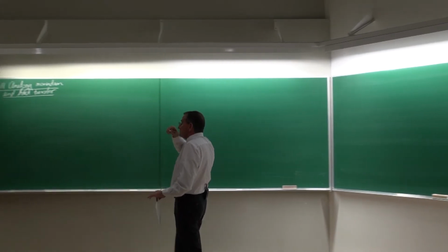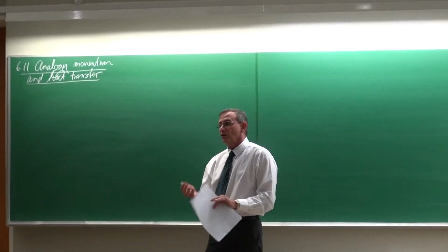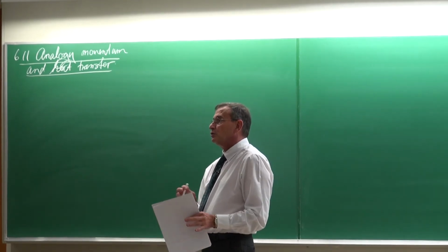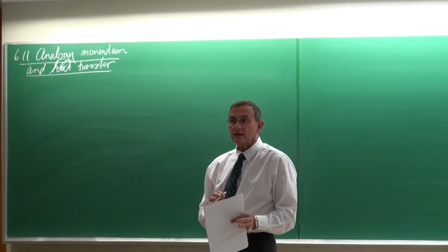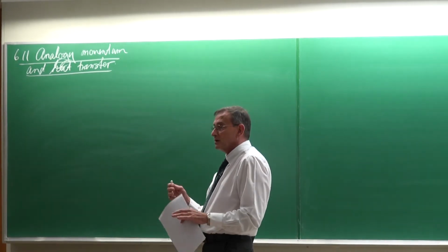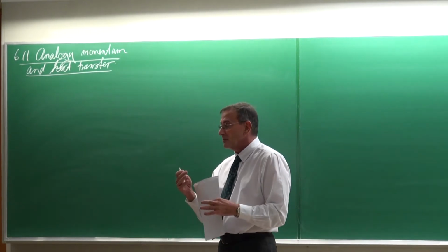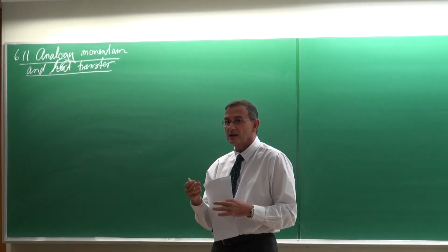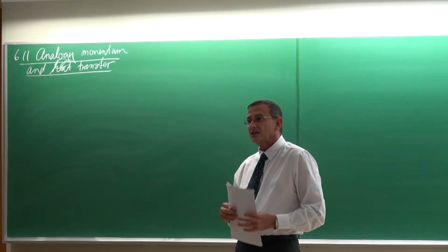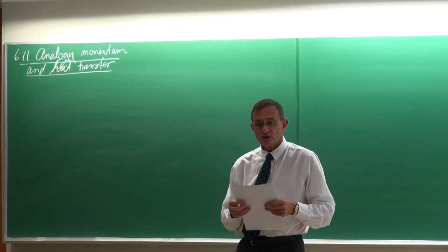And specifically, the Prandtl number actually tells us the ratio of the velocity boundary layer to the thermal boundary layer. And we've looked at three different scenarios of the Prandtl number. The Prandtl number equal to 1 means that the velocity boundary layer is the same thickness as the thermal boundary layer. And then we've got the other two cases of Prandtl numbers larger than 1 and Prandtl numbers smaller than 1.